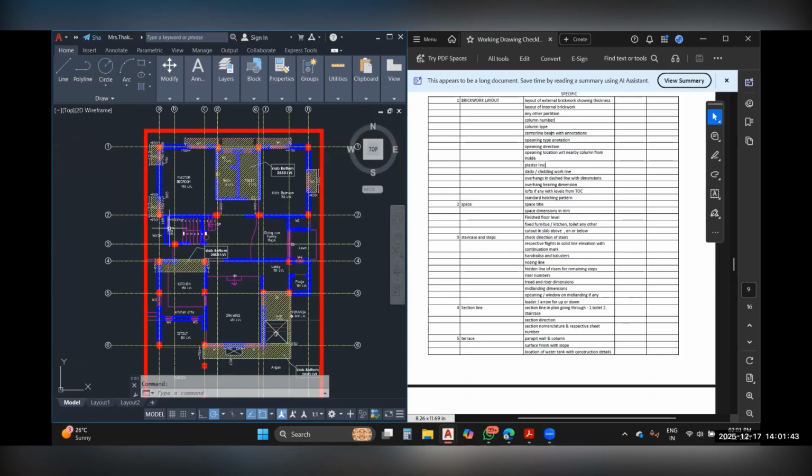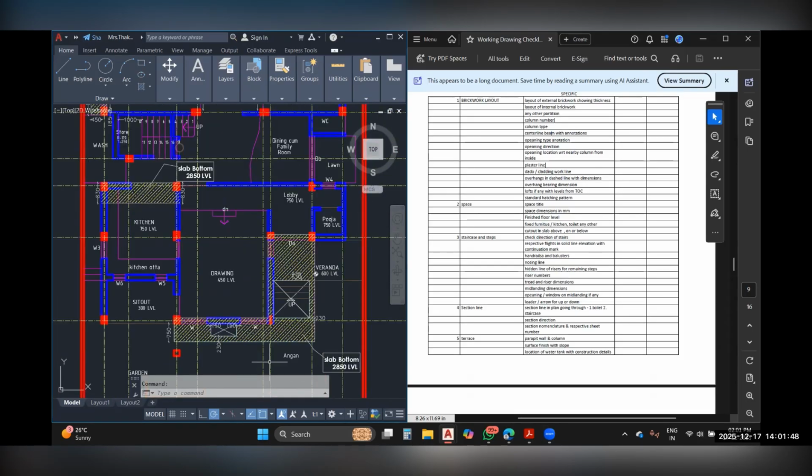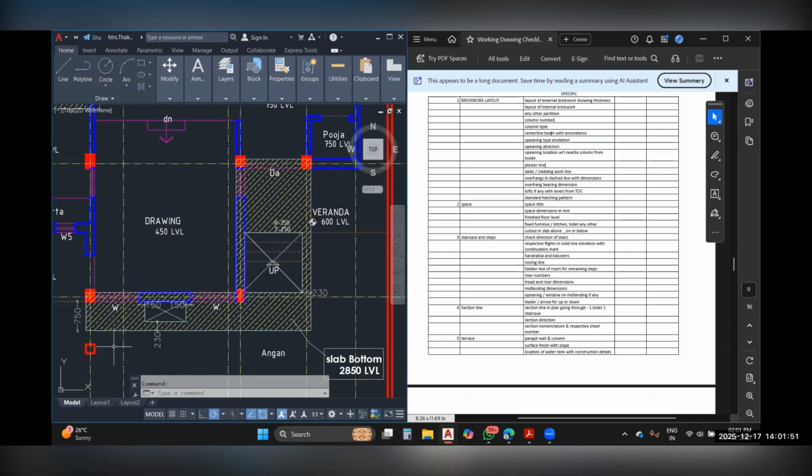So here is another example of a plan representing various slabs at lintel level. Here you could see that above these openings, W representing the windows and the door, you have a cantilever slab attached to these columns and lintel beams projecting outside in order to protect the openings from the rain. In such a case, you can even show these lines dotted.